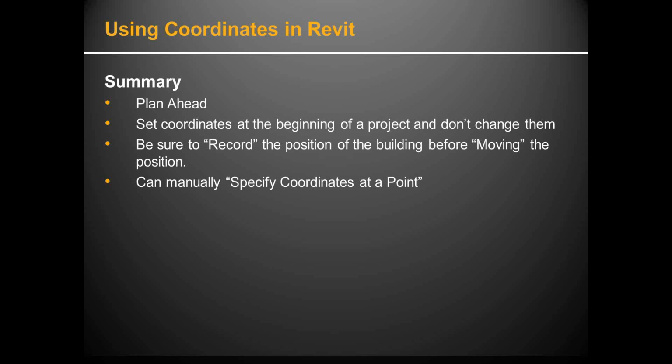So I would say, Juliana, if you're having that problem again, what I would do is, if you can't convince the architect to go about doing it, go ahead and on your own group those buildings together, make them their own individual links, or make them one link to the same building and record it a bunch of times, and then you can set up the coordinate system based on that. That should save you some time. Hopefully that clears things up.